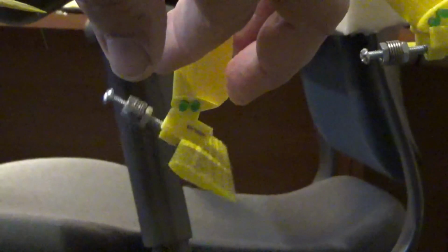Okay, here's the counterweight. I haven't glued this in yet, so I could take it in and out, but anyhow, I picked different lengths of screws and numbers of washers until this thing was approximately level, and I have some adjustment one way or the other. So this is a 1.25" number 6 screw. There's 2 nuts on there, 5 washers, and it's got some adjustment one way or the other, and it's approximately level, so I can tweak it. So anyway, that's how I came up with the counterweight.